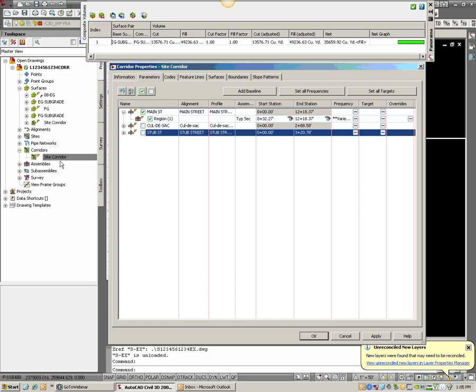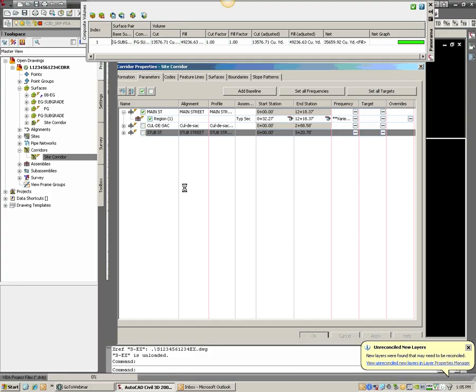Again, a way to speed things up is you're going to at some points want to turn off the automatic rebuild so that if you make any small change to your assembly, it doesn't recalculate everything. Most of the chain reaction, you can stop by just turning off your rebuild automatic for your site corridor. But I can uncheck certain parts of my corridor and do that.